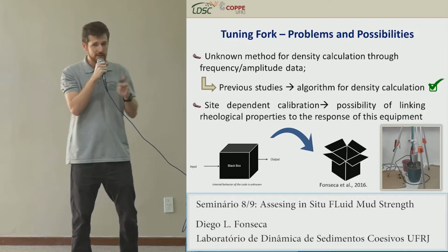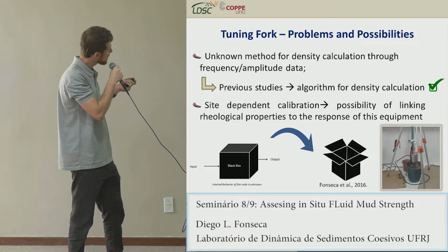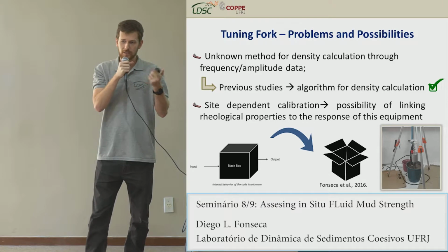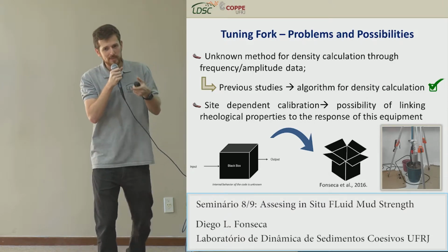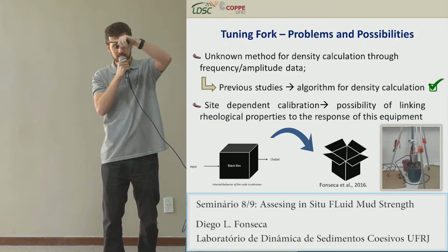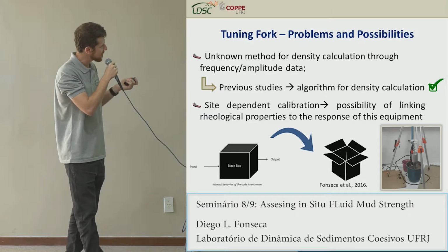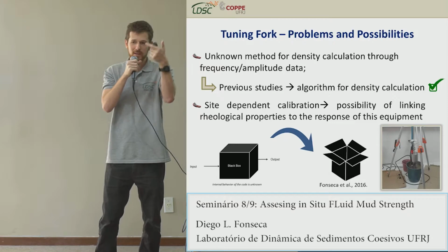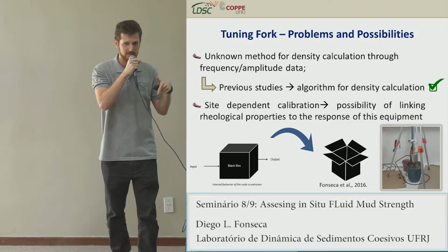And the reason we did this was because, if the calibration is site-dependent, it means it depends on the rheology for calibrating frequency and amplitude into density. So maybe with this calibration procedure, we are able to estimate rheology.